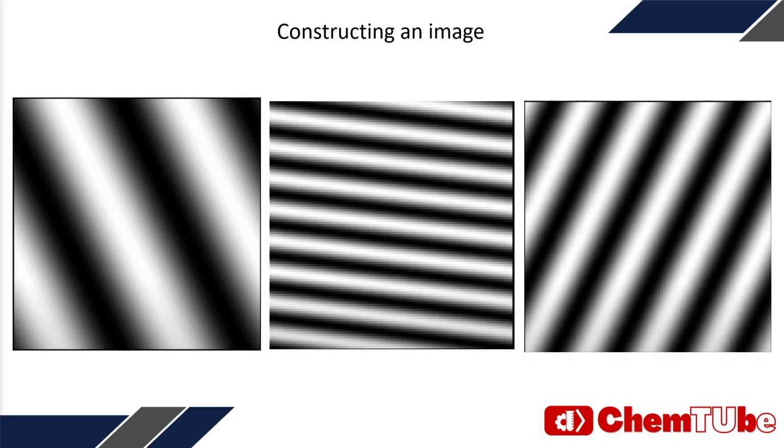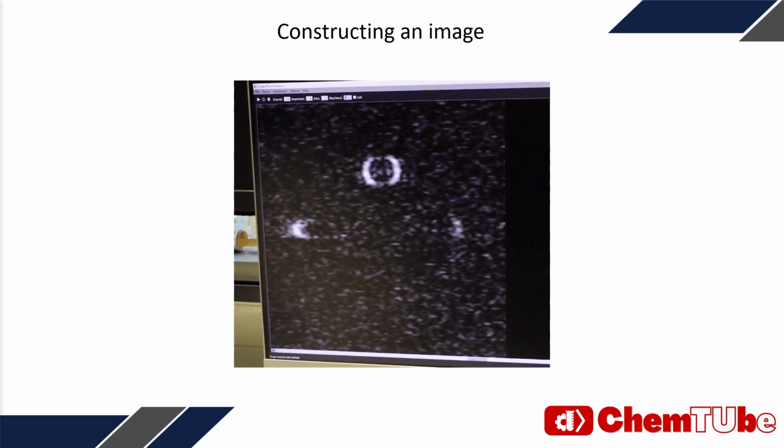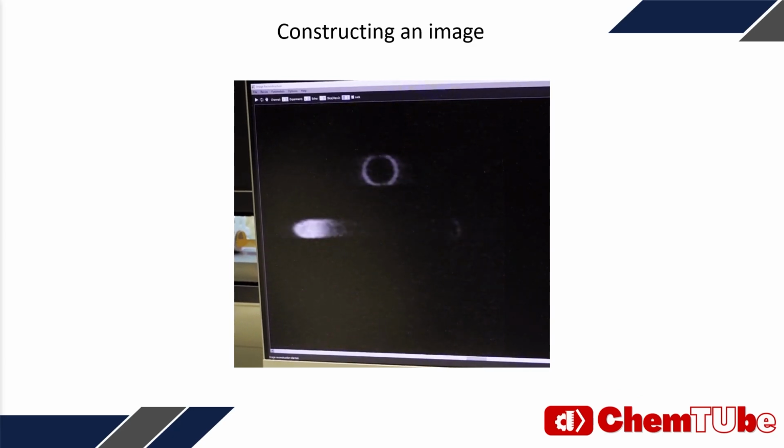By sending many different types of patterns for the current slice using the gradient coils, the MRI creates a weighted grayscale image, combining all these patterns based on the signal received. This is exactly the reason why at the start of imaging you can see a lot of noise, which is filtered out as more patterns are added together. Finally, you get a 2D grayscale image of a slice.